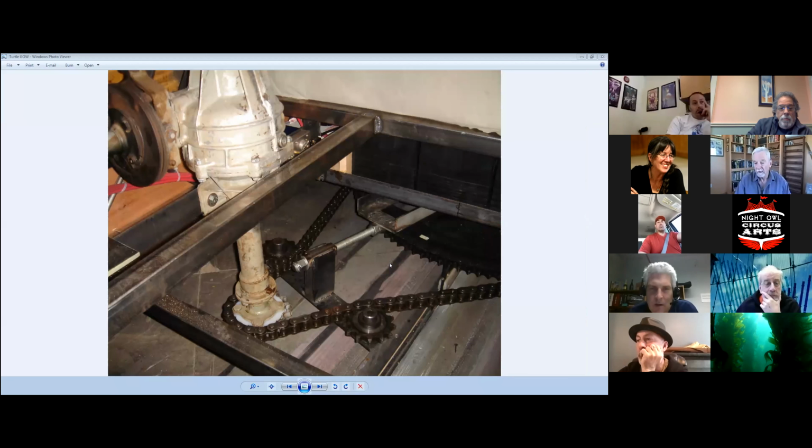I'll share this. It's going to be a little hard to understand what's going on here. This is a turtle that we built specifically for trucking Grapes of Wrath. It consists of a 3-foot diameter number 80 roller chain sprocket sitting on casters, with a blade welded to it that you can see right here. It's got UHMW on either side, and this is the track it runs in. You can see the cable right there. It's only 3/4 inches deep, but in this case, we lined it with 2 pieces of flat steel.